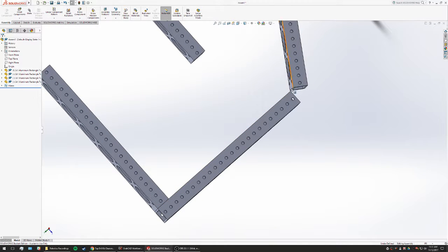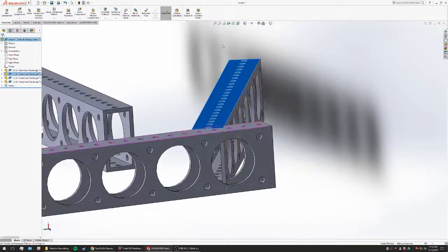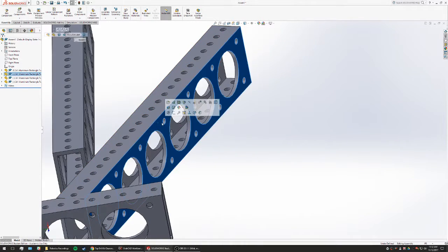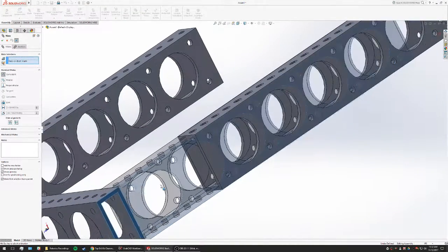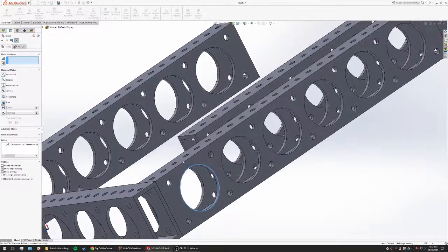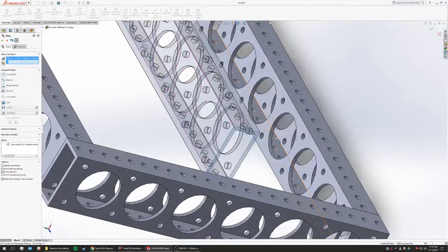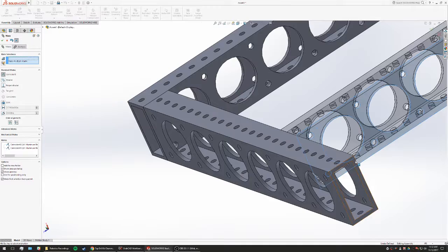So you can see I actually made a mistake here. See how it's not parallel? It's supposed to always stay parallel. If you look here, or actually I haven't gotten to that step right. It's supposed to do that. So there's still just parallel surfaces here. So it can rotate, it can move around. If you want to restrict it, you have to mate those two ends. And so now all 3 move together, and the last part fits in like that. And then you just want to move it down to the end.